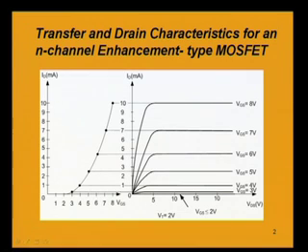For 3 volt, a small drain to source current will flow, which will be saturated after some drain to source voltage. That saturation voltage is equal to gate to source voltage minus threshold voltage. If we give gate to source voltage 3 volt, 3 minus 2, 1 volt is the saturation voltage between drain to source, at which the saturation current in the drain will flow.